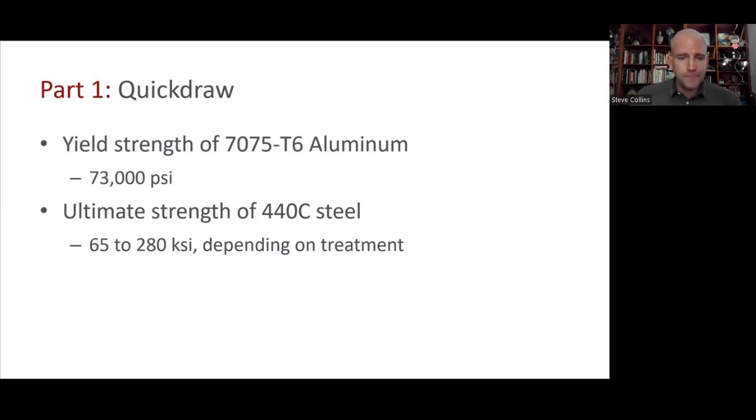You want to make sure that you've got those details of treatment right so that it will behave as you expect. Now, when you were poking around, you probably also had the opportunity to look at the elastic modulus and the density of this material. What were those values? Did they exhibit this big range? Probably you did not see such a big range because those properties are much less sensitive to heat treatment. And in fact, basically all steel has approximately the same density across all chemical compositions.